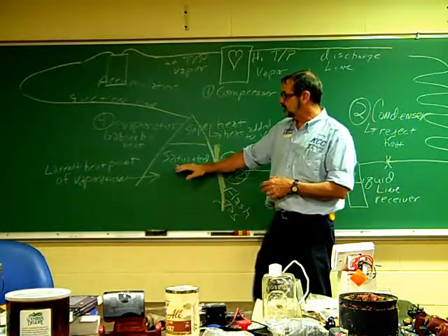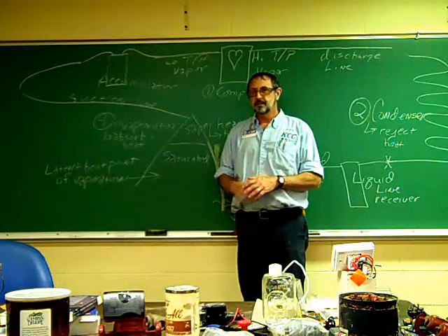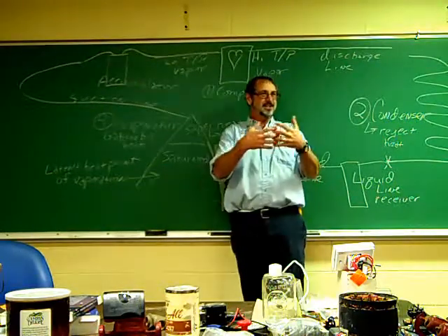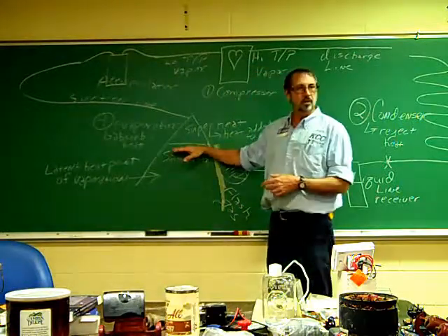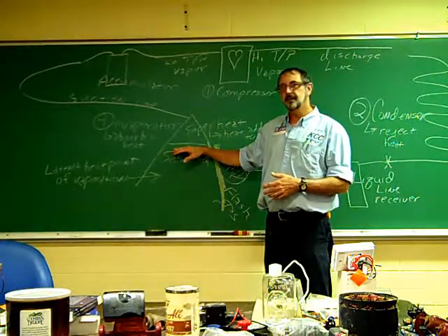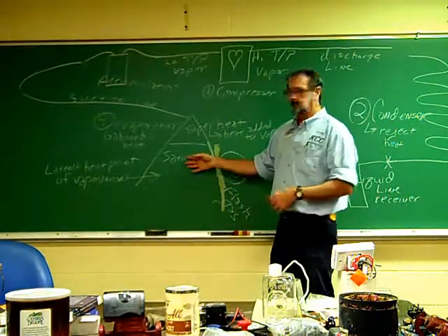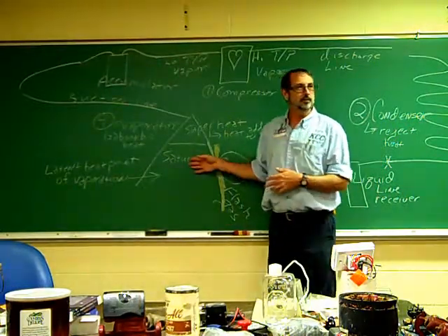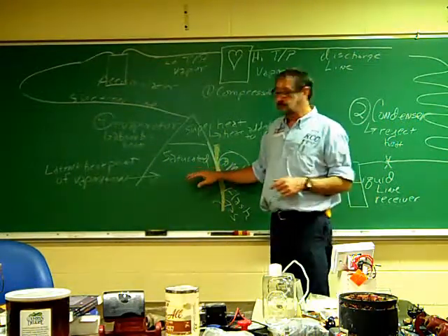It's in the state of saturation. We call it its latent heat point of vaporization. This simply means that it's in a state of saturation. We're going to try and turn it into a vapor. So the majority of our coil is in a state of saturation. Now, depending upon what type of system, how it's engineered, it could be anywhere from 50% to 100% of a state of saturation. That's just a variable. We're going to get to some of that.